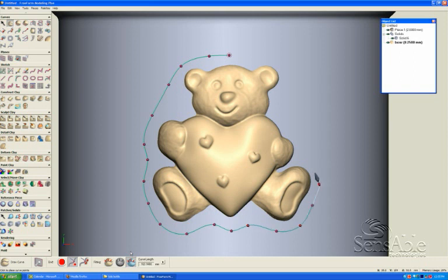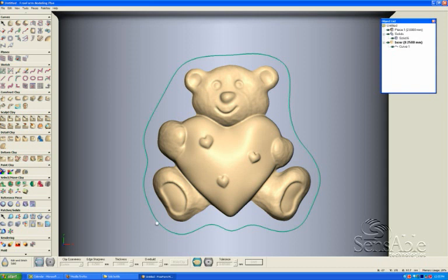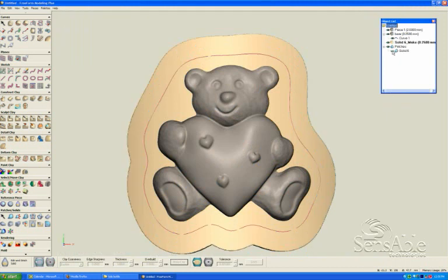But since we have two different types of geometries, we need to stitch this into the model. And since this type of model is not done in CAD, we need to do it in FreeForm and then stitch it into this model afterwards. So what I'm doing now is creating a trim line for this model, and I'm going to delete the inside of this surface on the baby's bottle and thicken it with an overbuild to a voxel geometry.